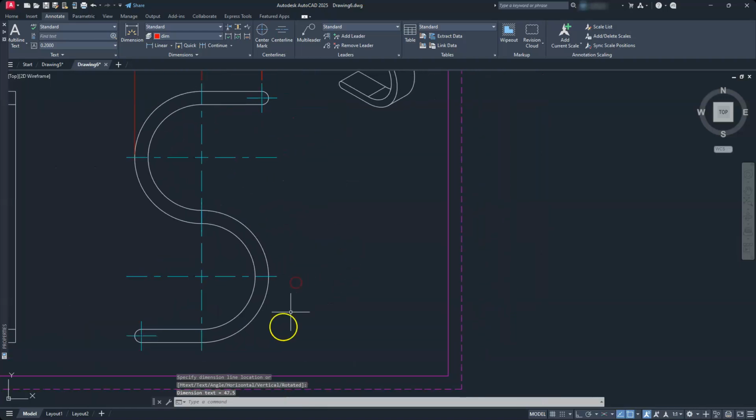Okay. Let's go ahead and put a couple more dimensions on this one. Let's put a linear going from this bottom endpoint. Let's do the centers on this one this time, so we're going to do it a little bit differently. So I'll put that dimension on. Then let's put another linear dimension from that center to this one. Let's go ahead and make sure that they're lined up.